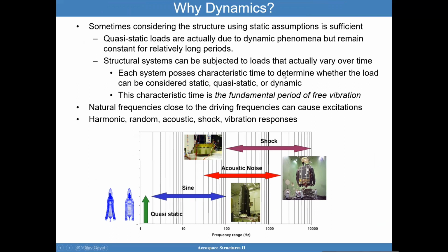Natural frequencies close to the driving frequencies can cause excitation. So if I have a natural frequency of a plate at 20 hertz, say, and I apply a loading that's close to 20 hertz in frequency, so I'm applying that load back and forth at 20 hertz, and the natural frequency of that plate is 20 hertz, then I'm going to cause something called a resonance condition. And that resonance condition can cause failure. So it's very important to understand that if I'm operating near a natural frequency, if the applied frequencies are close to the natural frequencies, it could cause failure.